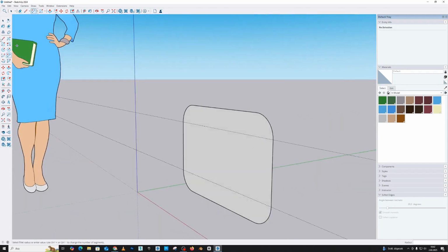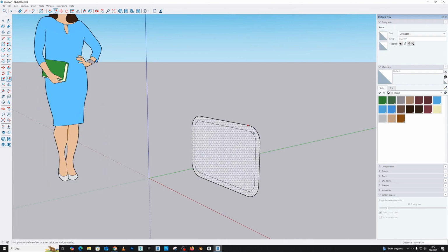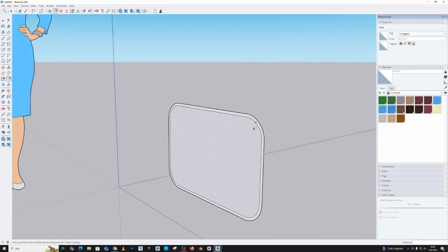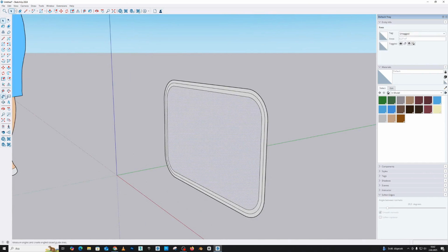Look, I drew this. Now, I've turned my screen around. Actually, I need two offsets here. I have one offset, friends. The offset inside, meaning the thickness inside, and also the part where the bevel is done on the outside edge. Now, normally, friends, when you select a surface, look here, when you pull it with the move command and the alt key, it makes a bevel there.